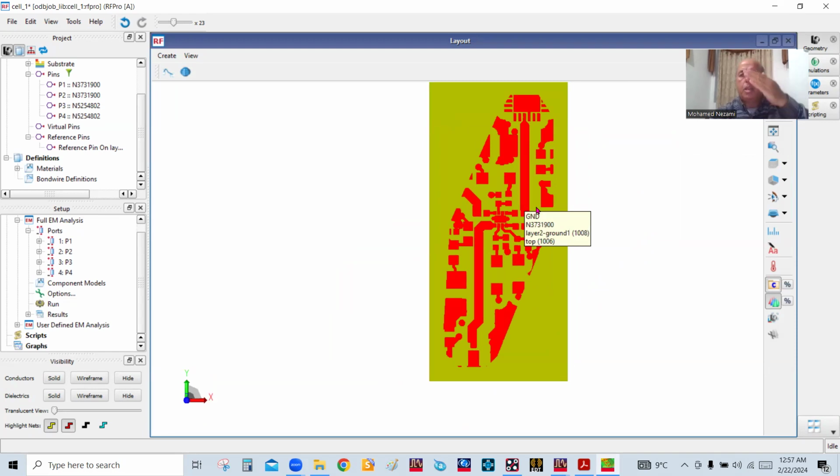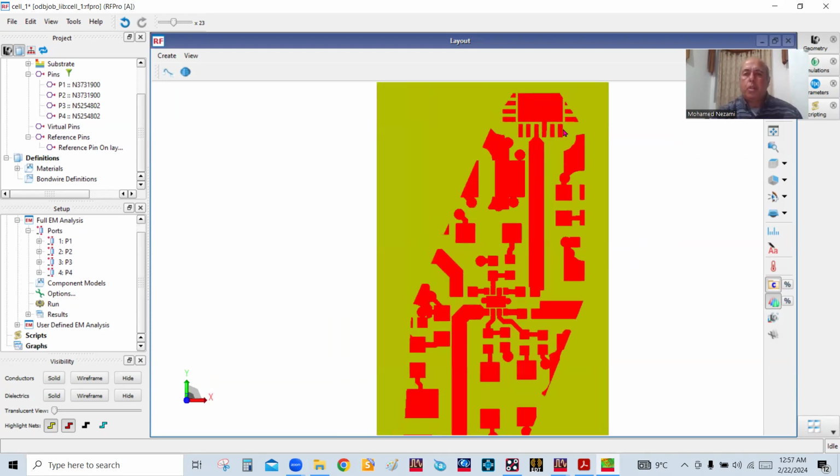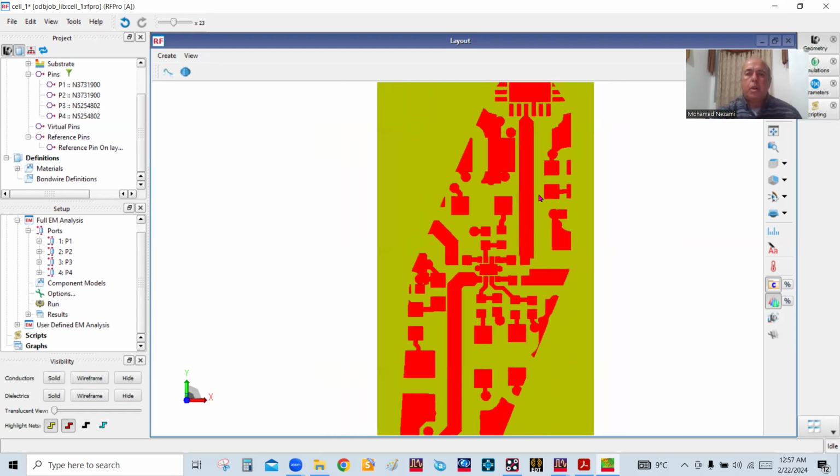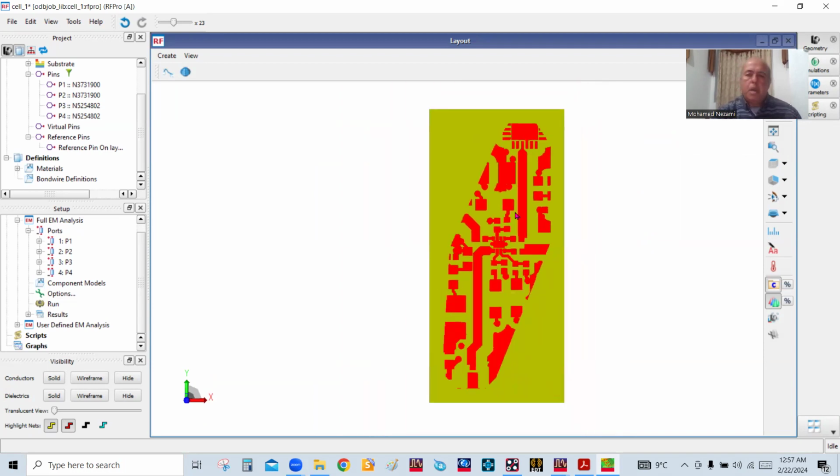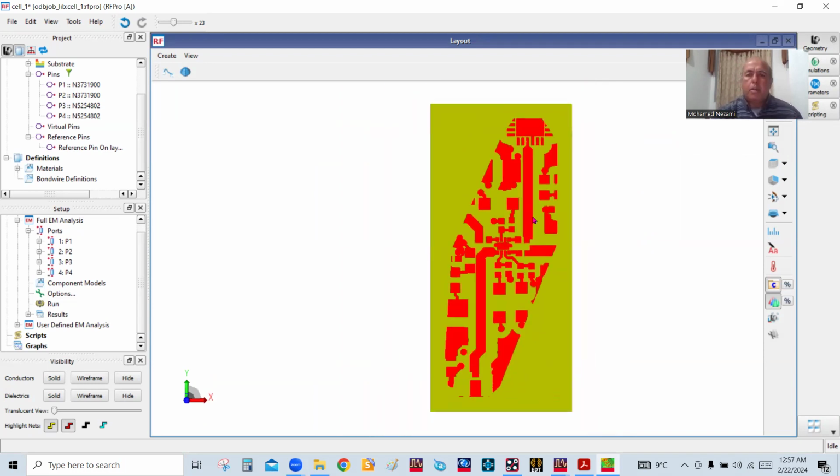So we go 3 gigahertz, phase lock loop, locked to an oven crystal, and then we multiply by 4 to get to the local oscillator value that we want, which is somewhere between 9 and 11 gigahertz. So we're going to run this in the S-band, up to 6 gigahertz, and see what we get.